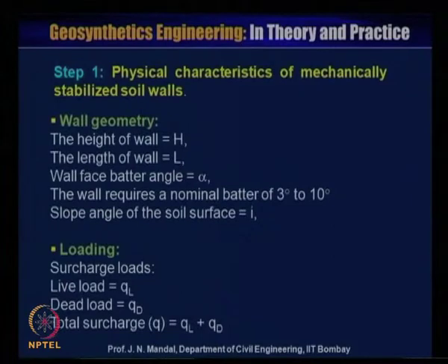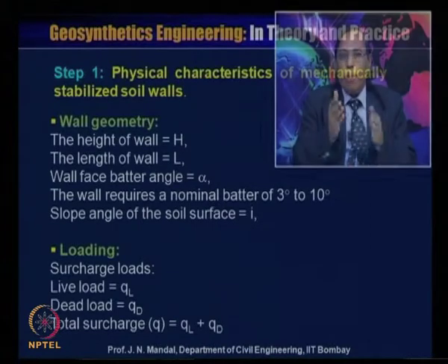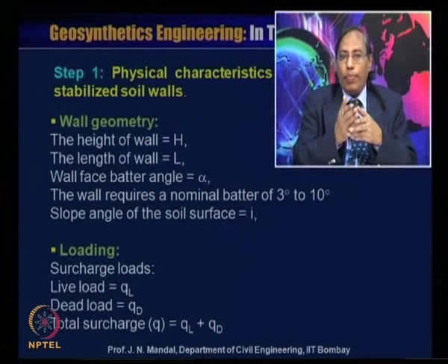Now step 1, you require the physical characteristics of the mechanically stabilized soil wall. So you require first the wall geometry. You should know the height of the wall, designated as H, the length of the wall, that is the length L, and the wall face batter angle, alpha.